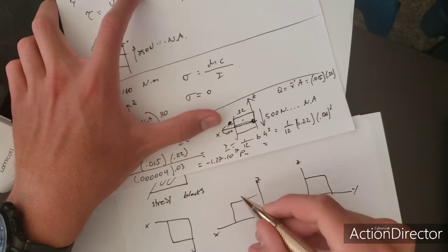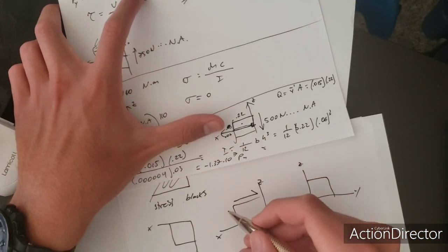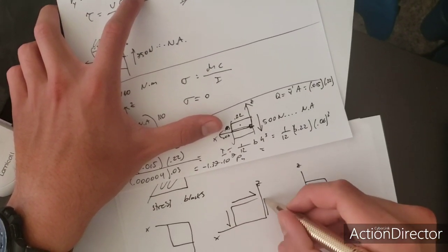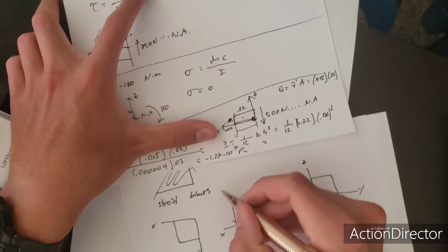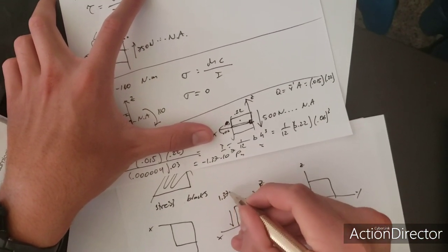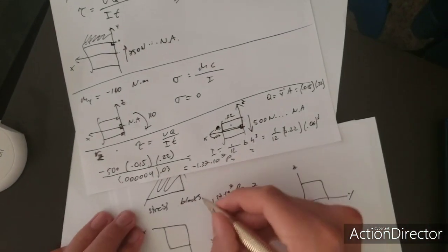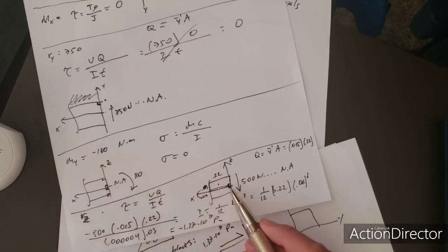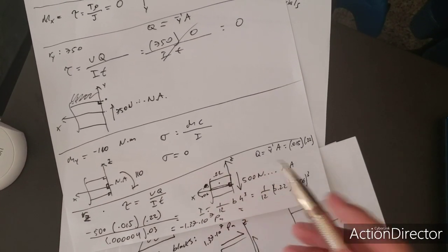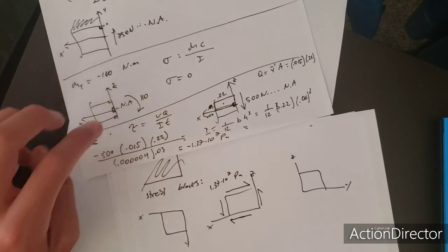It's going to go this way, negative z and negative x, and then just follow the arrows towards it, and you get the result 1.37, I can drop the negative sign, times 10 to the 7 pascals. And we disregard these because, like I said, it's only lying on the xz plane. Okay, last but not least, I think we need one more.